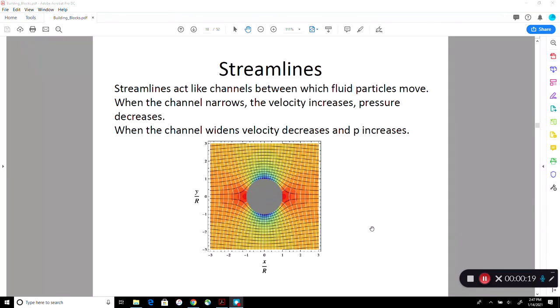We also showed that the combination of the conservation of mass equation, which we call the continuity equation, and the definition of irrotationality together leads to Laplace's equation, both for the velocity potential and also for the stream function. We also discussed what we mean by irrotational flow, also called potential flow in that context.